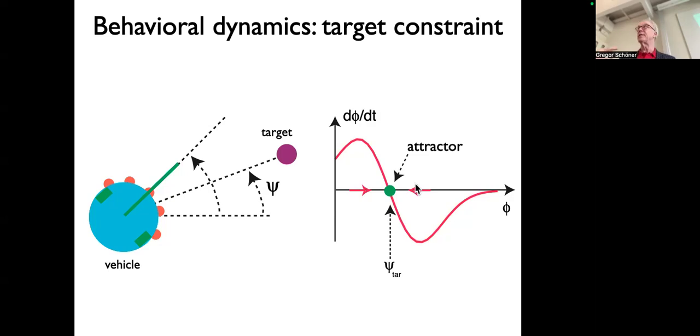A lot of these model cases around which planning algorithms have been evaluated are certain special situations. This is sometimes called the chicken cage. I don't know why it's called the chicken cage, actually. So where your target is, like you have a street, but that's blocked. And the target is sort of behind that block, right? And a naive controller would just go in that direction, then be stuck. And so you'd have to drive against that direction for a while to get around, right? That pushes the conflict between the two constraints of avoiding the obstacle and going to the target. And a lot of local approaches might have a problem. They always go in, then they see it's the problem, they go against, but then if they're far enough, they try again and so on, and they get caught in this kind of situation. And so we'll come back to that later, how to escape that.